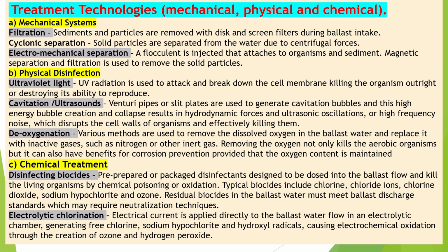B. Physical disinfection. Ultraviolet light. UV radiation is used to attack and break down the cell membrane, killing the organism outright or destroying its ability to reproduce. Cavitation/ultrasound. Venturi pipes or slit plates are used to generate cavitation bubbles, and this high-energy bubble creation and collapse results in hydrodynamic forces and ultrasonic oscillations, or high-frequency noise, which disrupts the cell walls of organisms, effectively killing them.